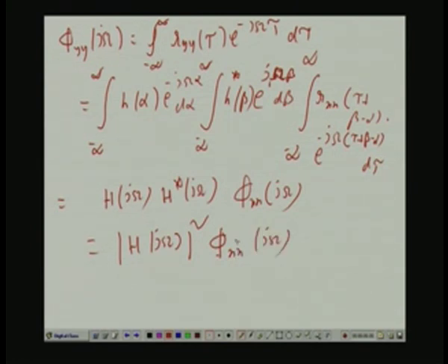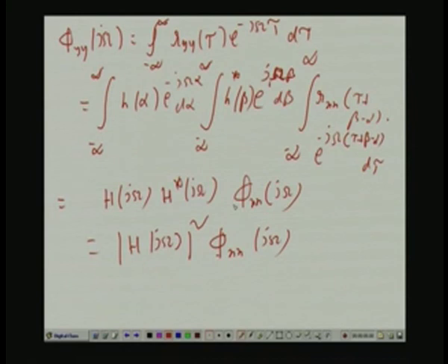This is a very important equation. This gives rise to the idea of filtering, that you can design a filter, a system, so that given any arbitrary power spectral density Φxx(jω), you remember this is a product relation. So, the output power spectral density can be shaped by your choice of the function. The input power spectral density is like this, but I want its value to go up at certain ranges of ω.